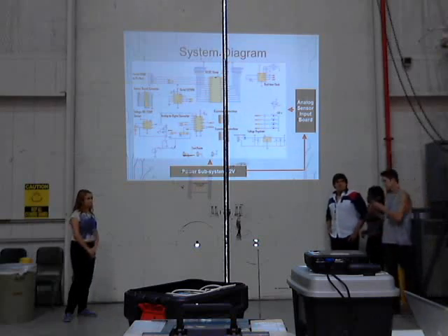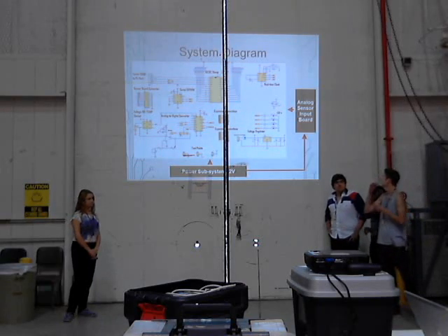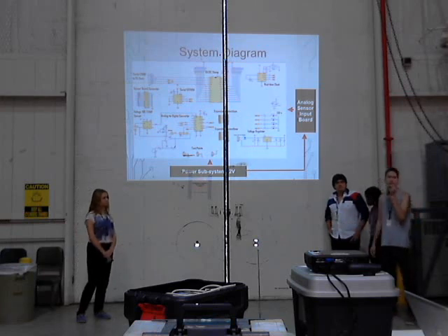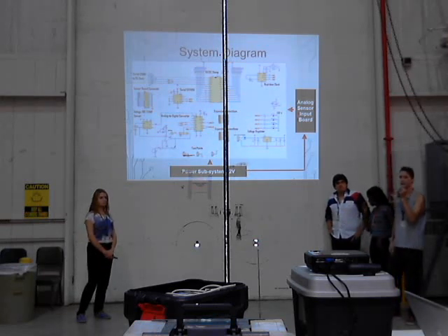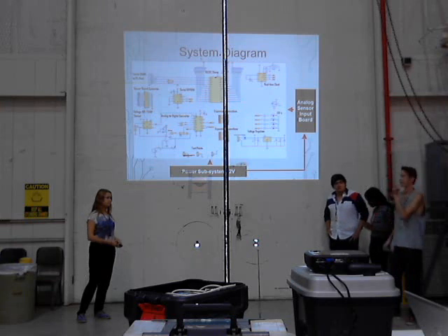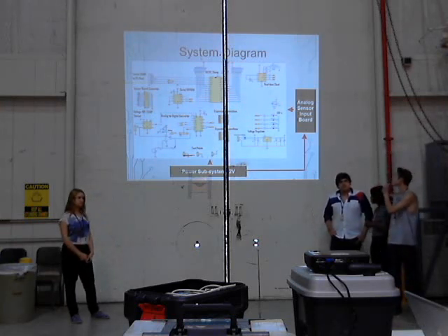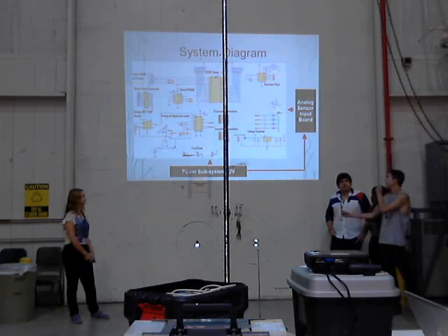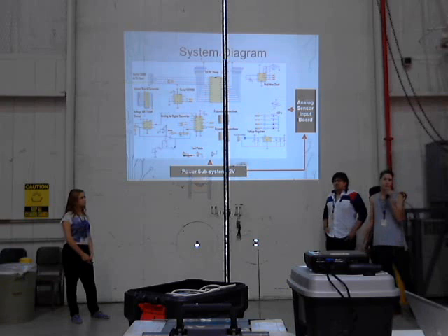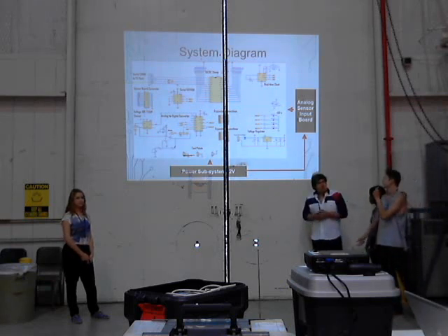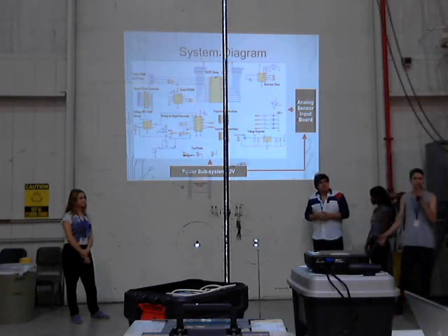So this is the schematic of our sensor input board. As you can see, we have the BASIC Stamp, which holds about 16 kilobytes worth of memory. We're going to be taking input data about once every 5 seconds. We have the analog to digital converter, which will give our atmospheric pressure readings, our temperature readings, and our humidity readings, convert them to an ADC scale, and then we can plot it in Excel and get our graphs.